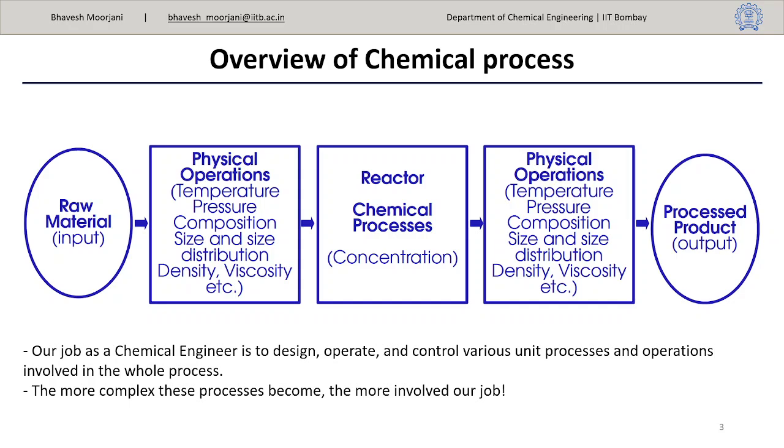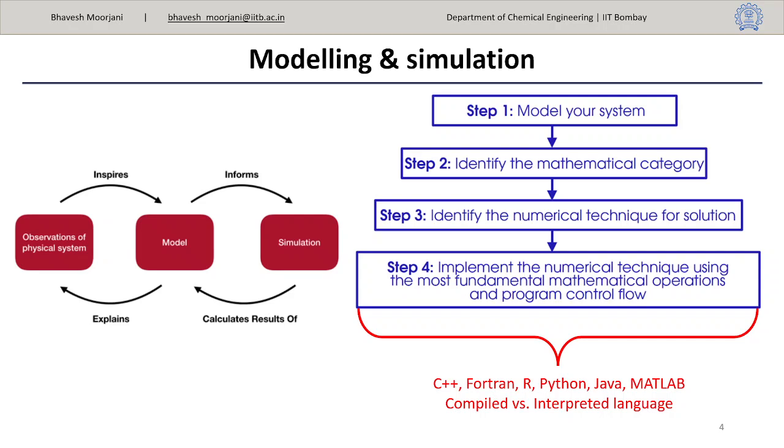Then you can use your heat transfer equations, which is nothing but Q equal to UA delta T LM, or m Cp delta T, and find out the change in the temperature of steam. Once you have the overall heat transfer coefficient, you can put them into UA delta T LM to find the area of your heat exchanger. That represents a simple model for your heat exchanger. When you have such simple equations in your model, you can simulate it by hand also.